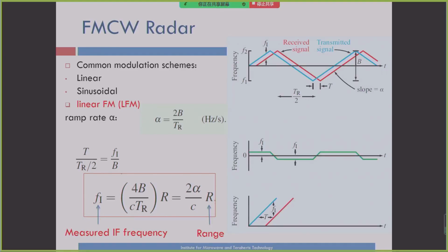So previously we introduced CW radar and pulse radar, and the pulse radar offers better signal resolution than the CW because it separates the transmitted signal and the received signal, so there is no interference between those. However, the CW radar has no range but high Doppler discrimination. Alright.